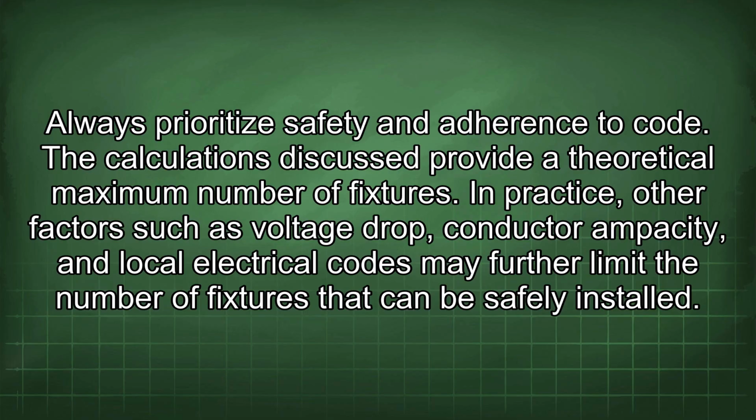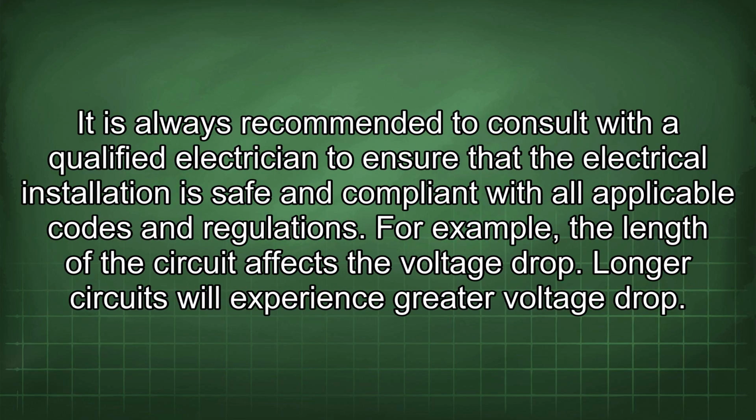The calculations discussed provide a theoretical maximum number of fixtures. In practice, other factors such as voltage drop, conductor ampacity, and local electrical codes may further limit the number of fixtures that can be safely installed. It is always recommended to consult with a qualified electrician to ensure that the electrical installation is safe and compliant with all applicable codes and regulations.